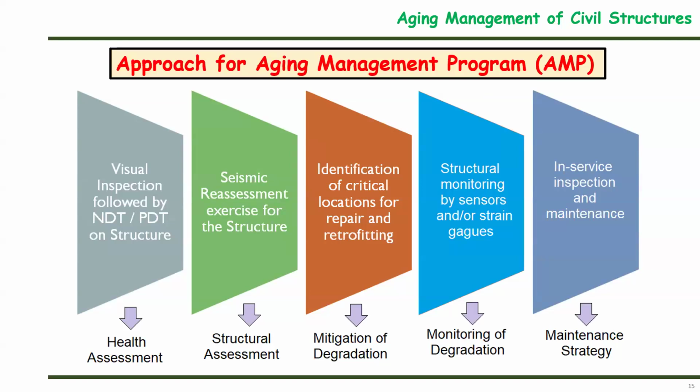They provide the quality of in situ concrete in the structure, the compressive strength of the in situ concrete, and information related to chemicals in the concrete, like chlorides, sulfates, and pH of the pore water solution. They can also provide information pertaining to the probability of reinforcement corrosion.